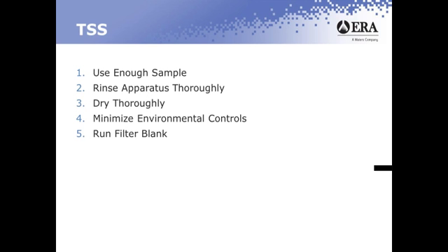To address these points, we're going to talk about using enough sample and what that means. We'll talk about rinsing our apparatus thoroughly, drying your samples thoroughly, minimizing your environmental effects, and running filter blanks in order to help with the environmental controls.